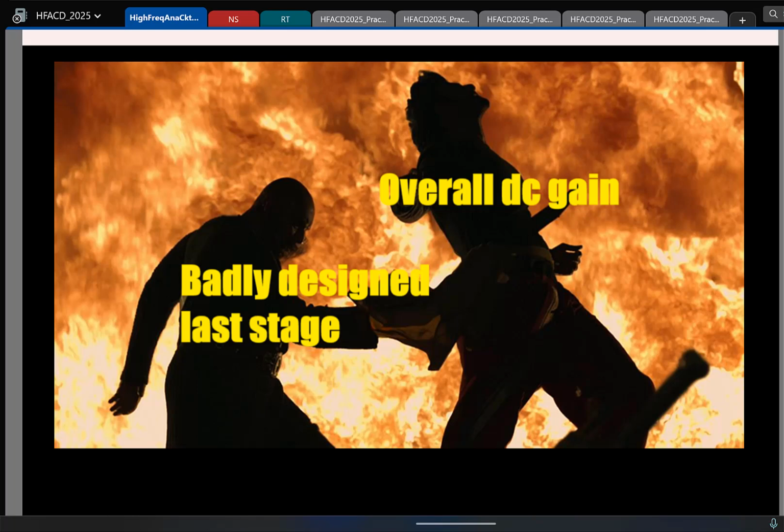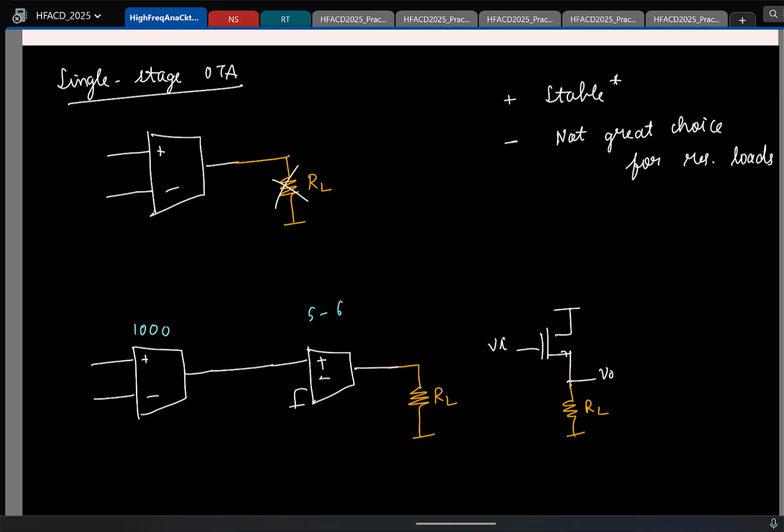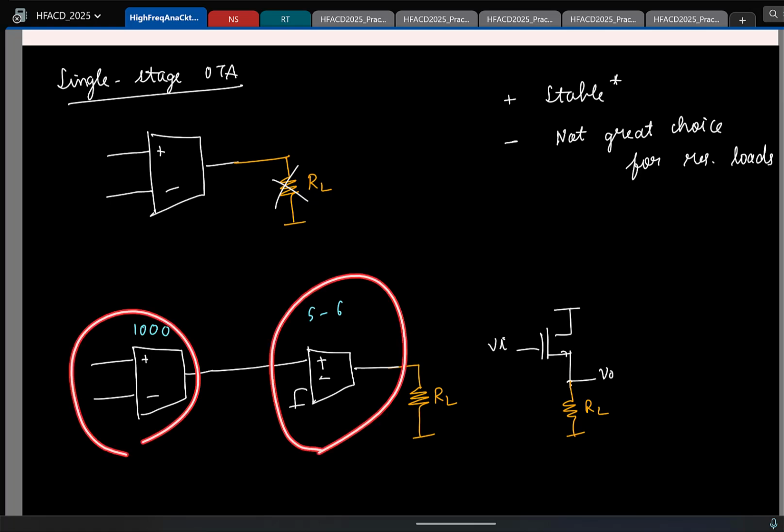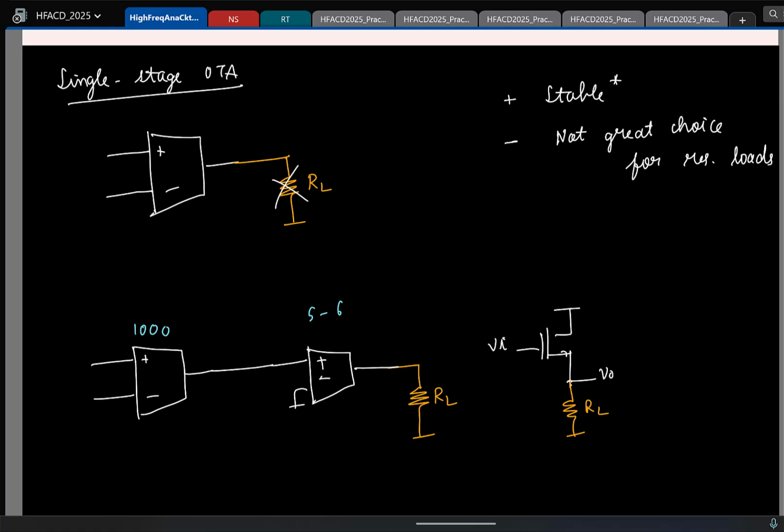So let's move on. So now you know what to do with this. So let's say now you see that this gain is also not good enough. What do you suggest we can do? Let's say you design this, you put one more stage, this gain is not good enough. That's all. I mean, it's like Bollywood releasing sequels after sequels. You can also put one stage after the other to increase your gain, and you can keep doing it. Okay.